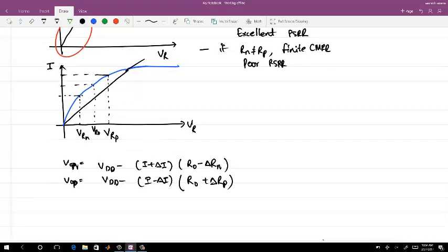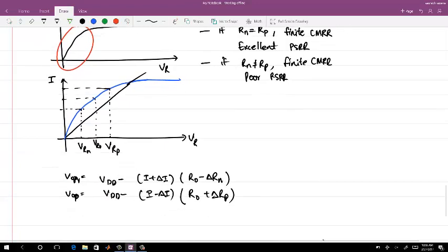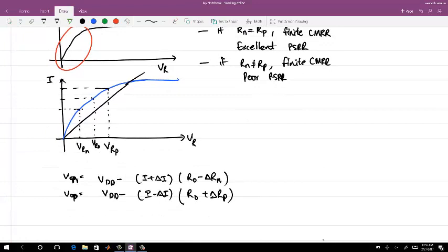But the thing is that at a given oscillation frequency, you are having a given I naught current, and you are switching all the I. So whatever amplitude you get, that amplitude will be fixed. It doesn't change, it is not linear with your oscillation frequency as such. The other thing is your PSRR is going to be bad. You can work out how the noise actually translates.